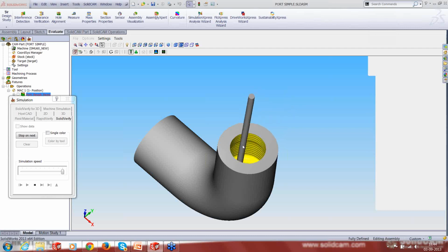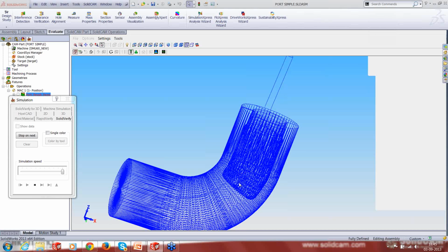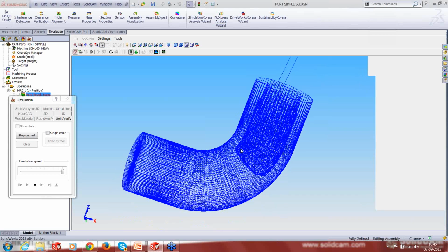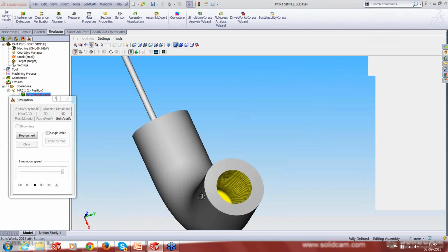Because if you remember, in our regular 5-axis machining strategies, you have to define curves and points and all those things and define what kind of a tilt you would need to cut this part, and then the angle of the curve would determine how deep your tool would go. All that is out. It's straightforward. Select the surface, select the tool, select the parameters and hit calculate button. Gone all the way up to here. Now it's finished that side, and now it's come automatically on the other side.